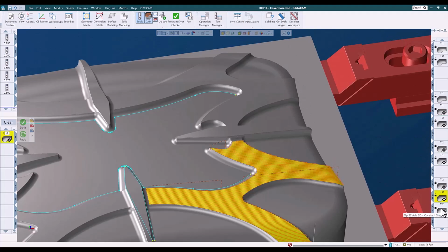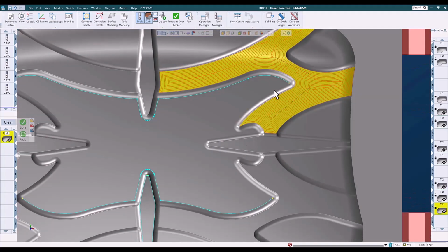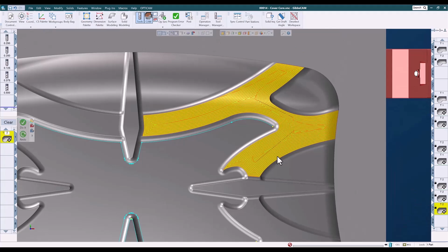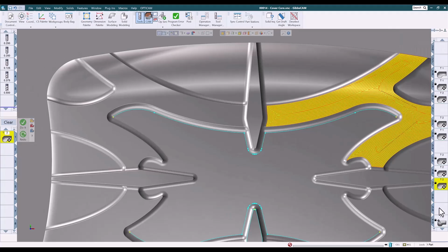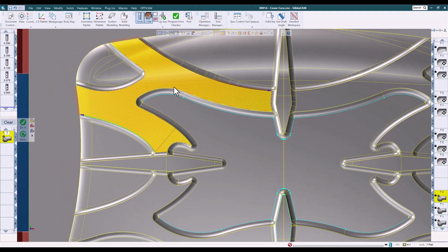Here's an advanced 3D constant step over pattern. This flows perfectly with the area to be cut and only has 2 retracts. This would work very nicely for this shape. And while we're looking at these, let's check out a few of the multi-axis or the 5-axis options for these features. Of course, all of these are set to output 3-axis toolpaths. This is a multi-axis toolpath based on surfaces, and the pattern is a morph between 2 curves. This is a beautiful toolpath that morphs from one edge to the opposite edge and gives me complete control over retracts.